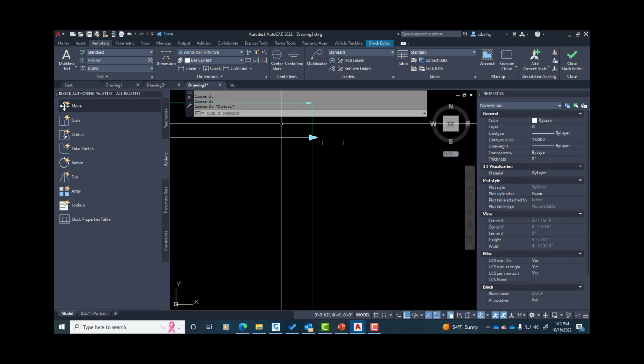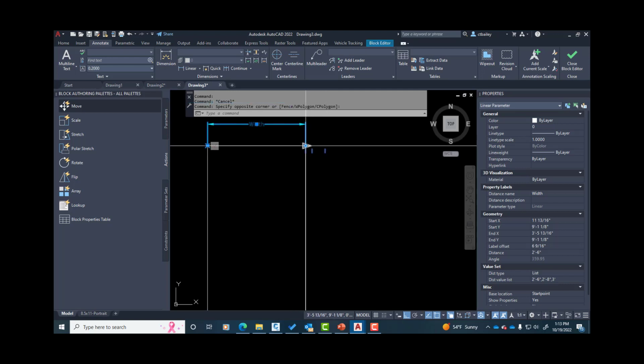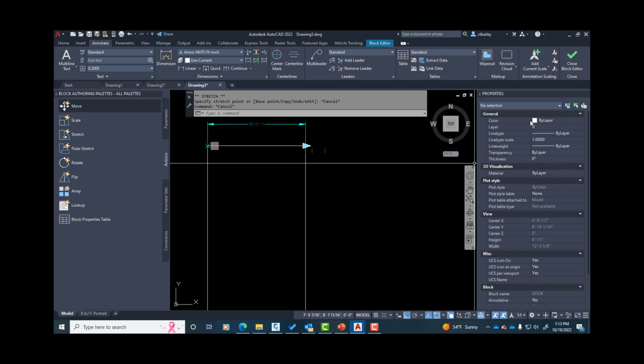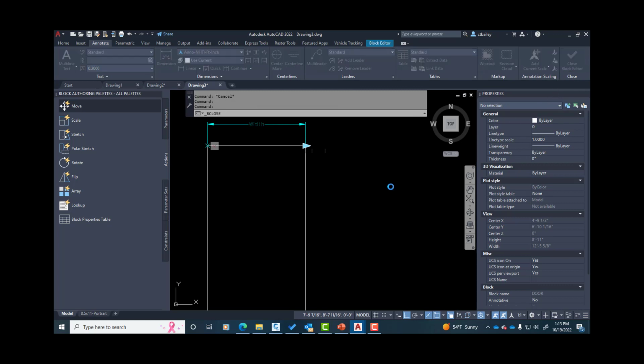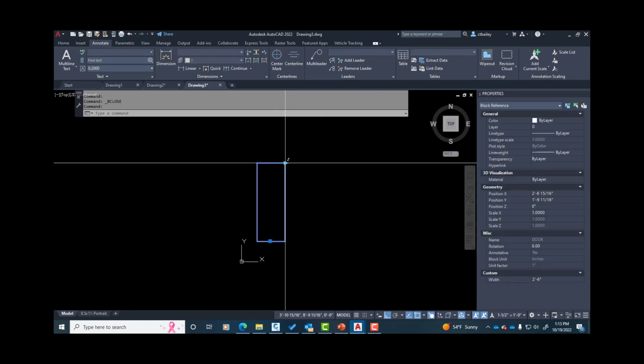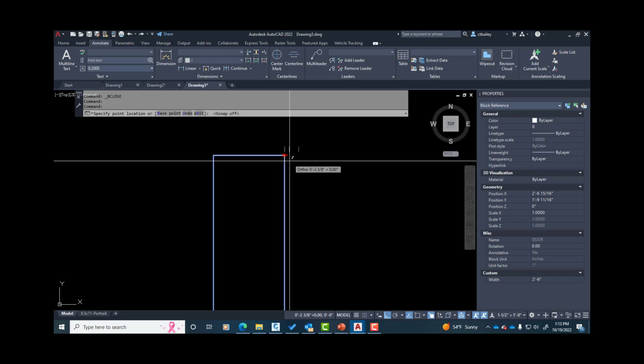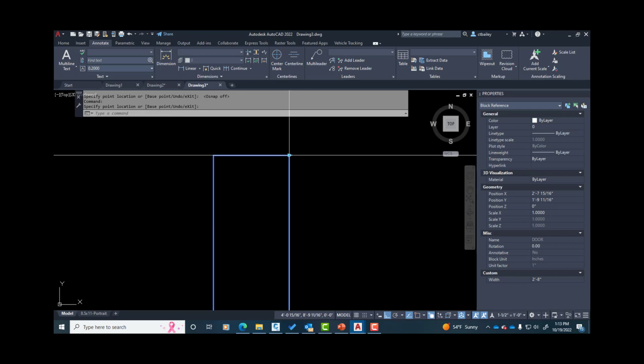Notice we now have, instead of a little range bar, a tick there, a tick here, and a tick here. And so I can pull this out only to those options. Let's go ahead and try it. Close the block editor. There's 36 inches, there's 32 inches, and there's 30 inches. Okay, we only have 3 options. 36-inch door, 32-inch door, or a 30-inch door.